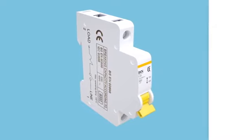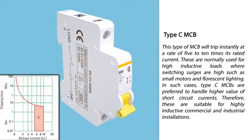Type C of miniature circuit breaker. This type will trip instantly at a rate of 5 to 10 times its rated current. These are normally used for high inductive loads, where switching surges are high, such as small motors and fluorescent lighting. In such cases, Type C are preferred to handle higher value of short-circuit currents. Therefore, these are suitable for highly inductive commercial and industrial installations.